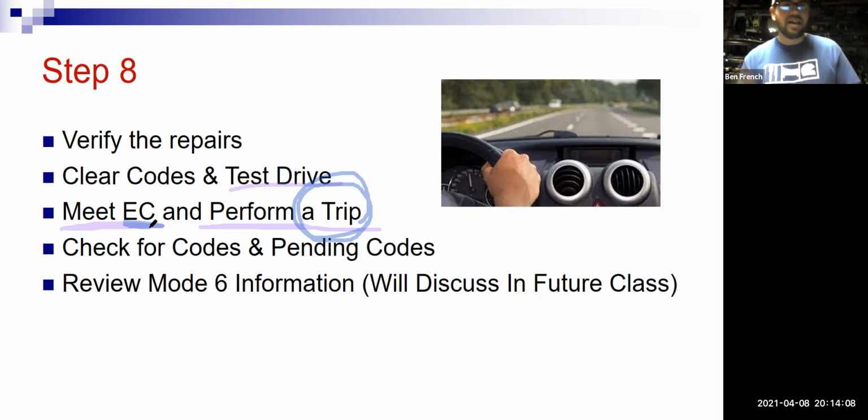It says, hey, how's that O2 sensor heater doing? Because it looks at its time to activity, right? And then it tests it out. And then you shut the car off. Then you're going to go on there, key on engine off, and check for codes. And here's what's key: you're also going to check for pending codes.